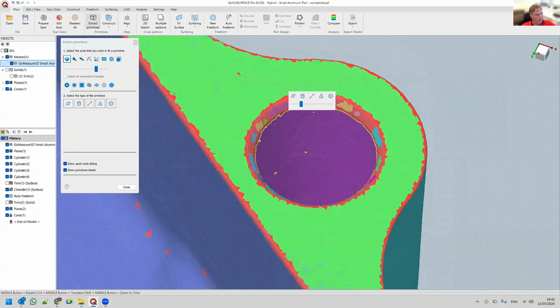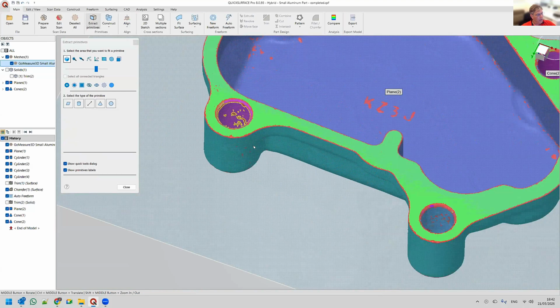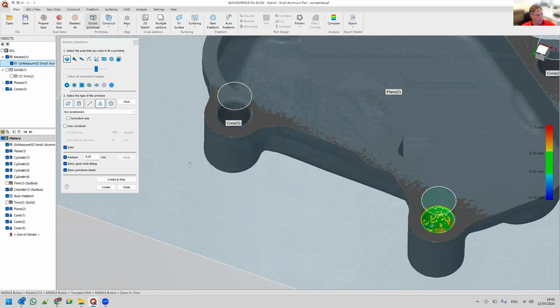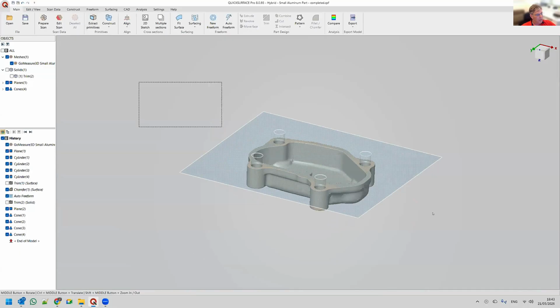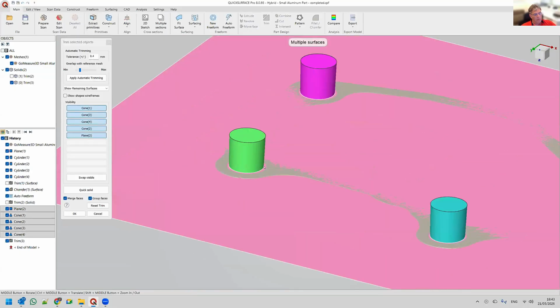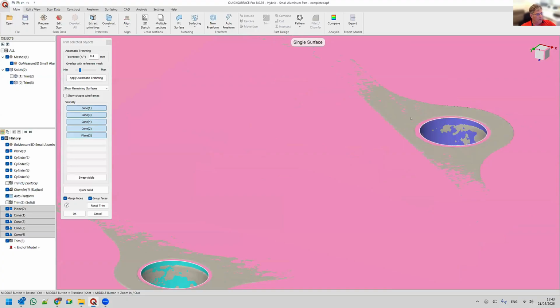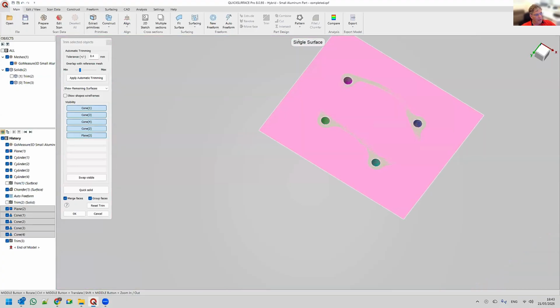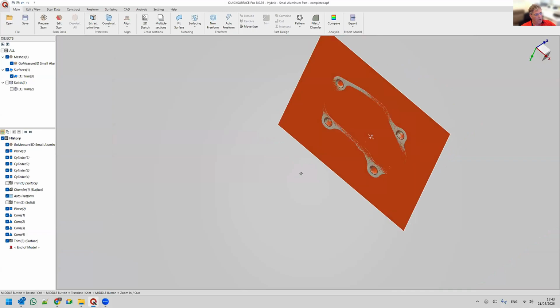And in this case, I will create these four columns here that I needed. We'll create and stay. We'll also recreate. So I have these four geometries. What I can do is just select everything and say, I want to trim. How do we trim? It's very simple. You just pick and remove what is not needed. You remove the excess surfaces, and you can see it tells me it's a single surface, and I can press OK. As you can see, I created what is needed for my main shape.